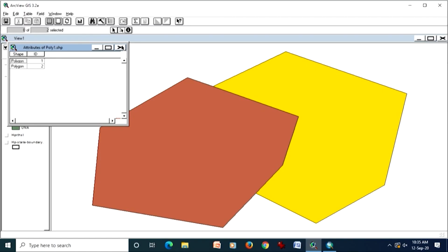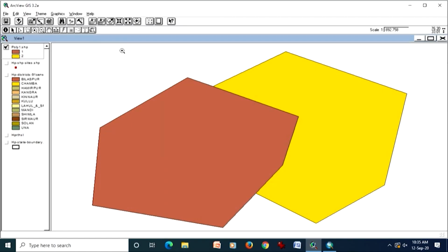If one is not building polygon topology and keeping data in the spaghetti model, then you would find a lot of gaps along this. The common boundary between the left polygon and right polygon has not been drawn or digitized twice, I have done it only once.